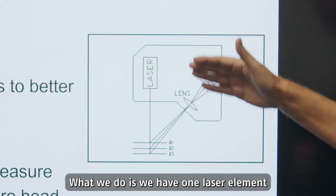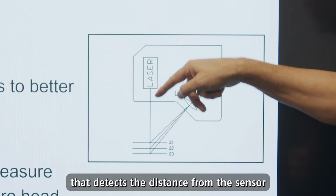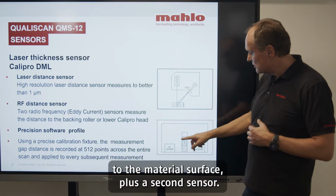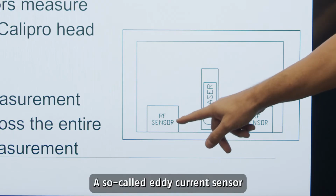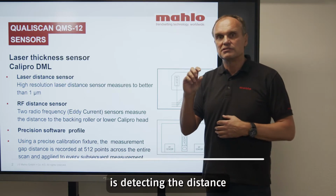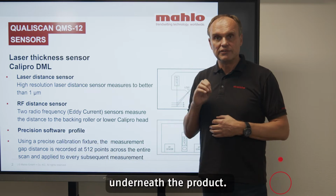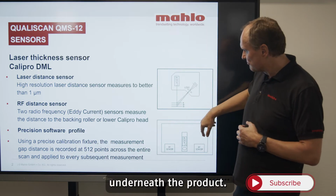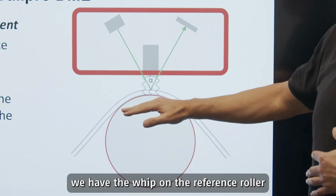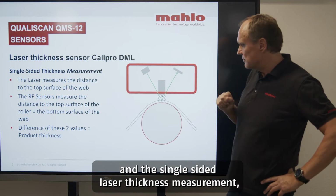What we do is we have one laser element that detects the distance from the sensor to the material surface, plus a second sensor, a so-called eddy current sensor, is detecting the distance to a metal reference underneath the product. If you look at this example, we have the web on a reference roller and a single-sided laser thickness measurement.